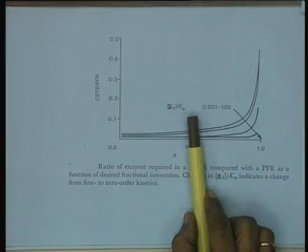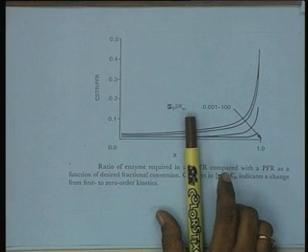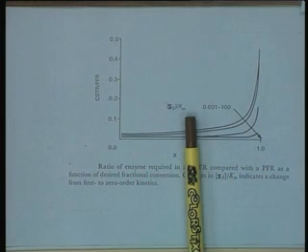For example, in the earlier phases, up to 90%, there is no major gain in using a PFR, but if you want a fractional conversion much higher than 90%, then the PFR becomes more and more a matter of choice.